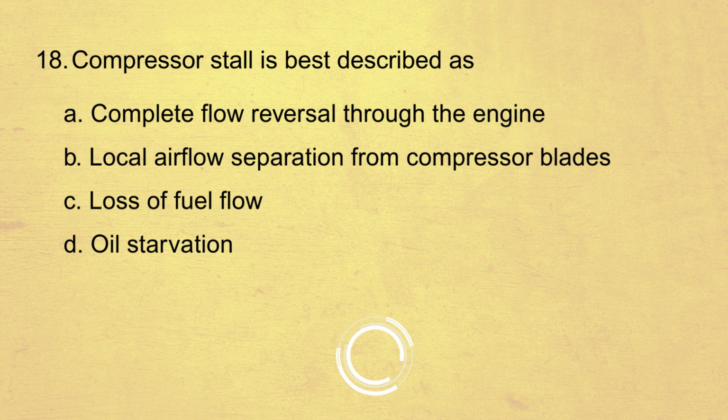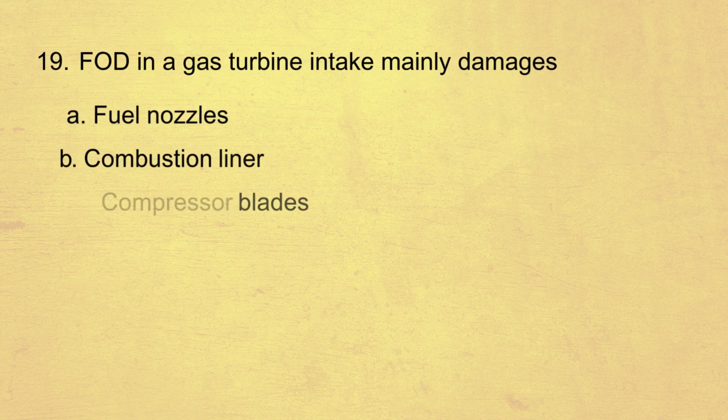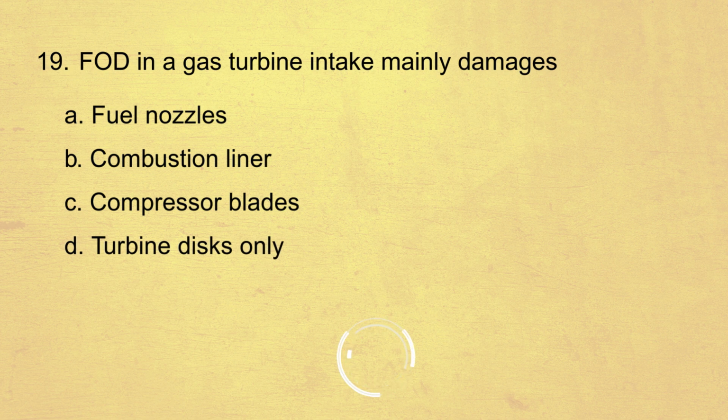Compressor stall is best described as local airflow separation from compressor blades. FOD in a gas turbine intake mainly damages compressor blades.